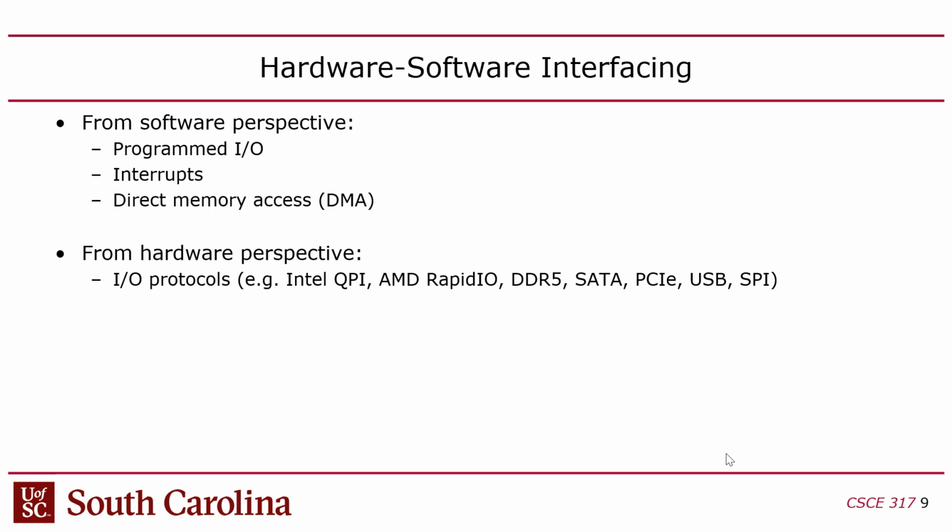But it also makes the performance non-deterministic. An operating system is always doing stuff. It's always taking control away from software and giving the control of the CPU to some other piece of software, or to some server, or to some interrupt. You never know what it's doing, right? So if you're writing something that says, well, I'm a cruise control system for a car, I got to adjust the power that the engine is putting out, and I got 10 milliseconds to do it. If I don't do it in 10 milliseconds, I'm going to speed up beyond what the driver set as the speed, right? Linux will not guarantee that anything can be done in 10 milliseconds.